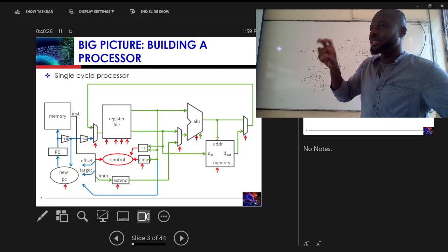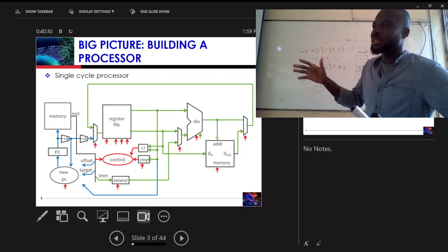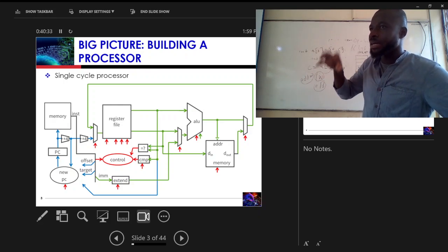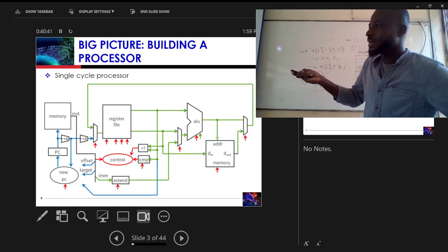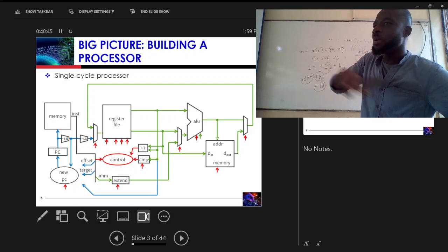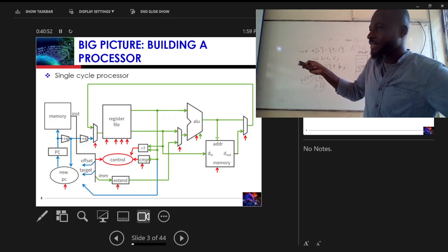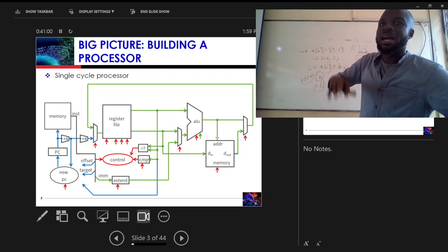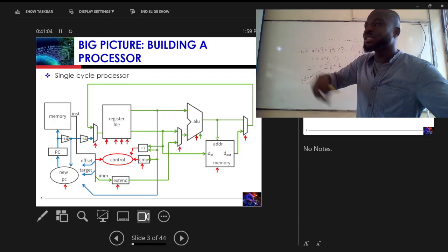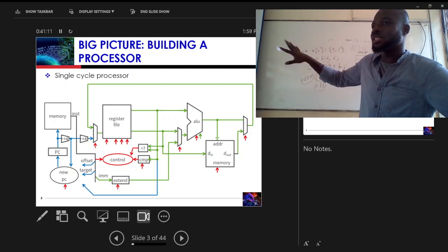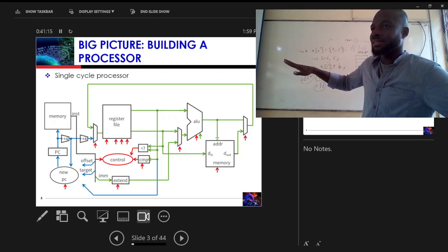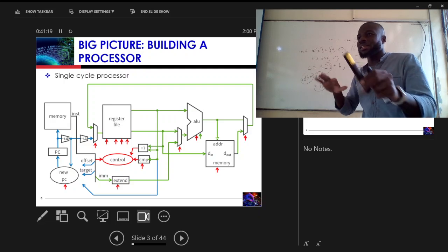Now, the disadvantage of the CISC is that because the instructions are so many, your hardware is very complex. Your hardware must have a lot of components. So, like here, we have memory. You see that the memory is routed to the register file. But because with the CISC we can read from memory and from the register file at the same time and then operate on them, it means that I need a way to connect this memory to this register file. It means that this register file cannot have only two outputs and stuff like that. This register file must be more complex than this. So the architecture of the CISC is more complex. The internal architecture uses more gates, more wiring and everything. But with RISC, because we are using very simple instructions, the internal architecture is very, very simple, and it uses fewer gates. So that's the difference between the CISC and the RISC architectures.